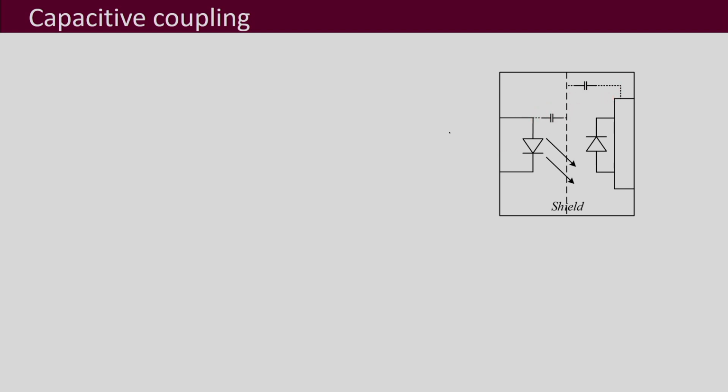current. Here on this side we may be giving a signal which is, let us say, from 0 to 5 volt, and on the other side, depending on these optocoupler based drivers, it may be connected to your supply, it may be VG, and this other terminal may be connected to the emitter or the source of the IGBT or MOSFET, and these levels are different.